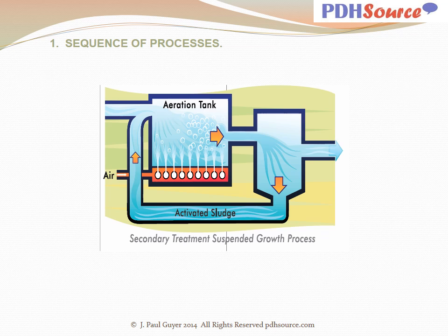Secondary treatment typically consists of mixing of oxygen with the wastewater stream in order to reduce the large molecule contaminants to small molecule contaminants that can then be released into the environment without any adverse effects. One of the most common methods of secondary treatment is the activated sludge treatment.